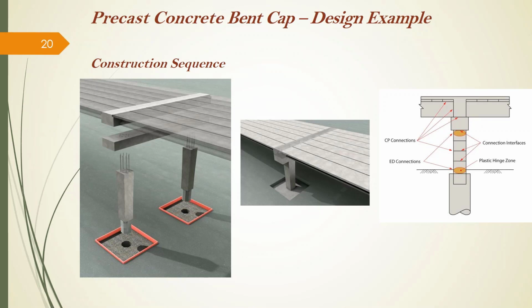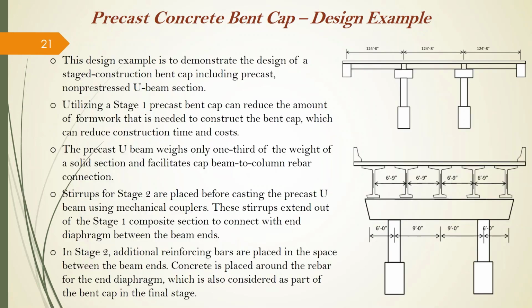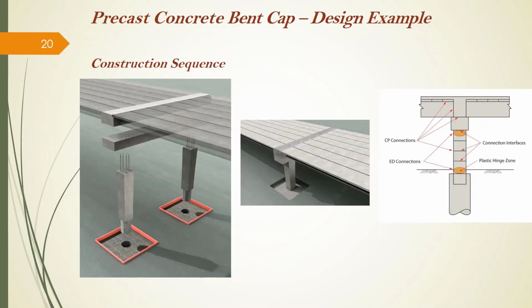In general, we try to capacity protect the elements of the superstructure, which we call CP. It's in the new ABC AASHTO guidelines that is out, revision 1, as Dr. Khaleghi showed in his slides. And also we try to confine the energy dissipations to the elements of substructure, specifically the columns. Next slide, please.